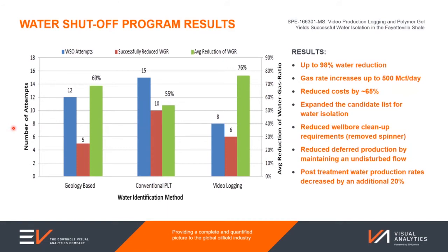The benefits of this are that rather than a highly viscous material, this is quite a light sealant, and it activates actually out in the fractures itself. So rather than trying to plug off the perforation tunnels or the well bore itself, it's by squeezing it out into the fractures and letting it set in those small tight cavities. That means there's very, very little cleanup and no restriction in production from the rest of the well. There's no need to go in and mill anything out. It's very good in terms of leaving open pathways for future intervention or production from other zones.